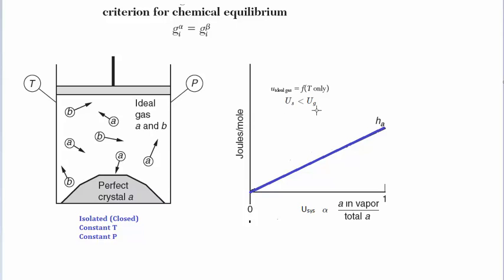And that's, if you remember back to internal energy, it's all the sum of all those molecular forces, one of those being kinetic energy. Gases have much higher kinetic energies than solids. So I hope that convinces you that it makes sense for this to be linear for an ideal gas.